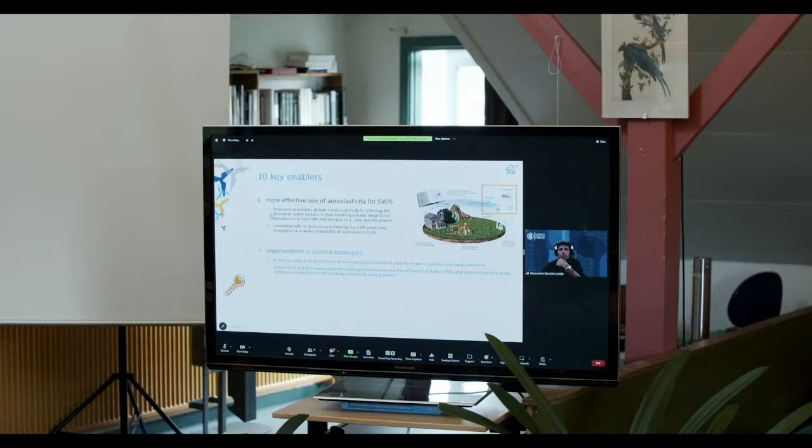We need to improve the aerodynamic design, especially with focus on low Reynolds airfoil aerodynamics in turbulent environments. This is relevant not only for performance, but also to ensure, for example, a better control when you design stall control-based machines, and also to reduce noise and to account, for example, for air density variation.